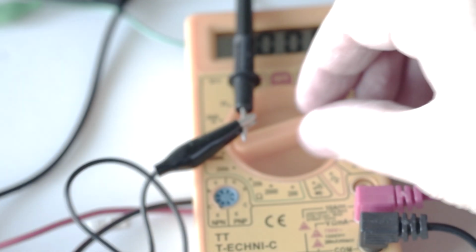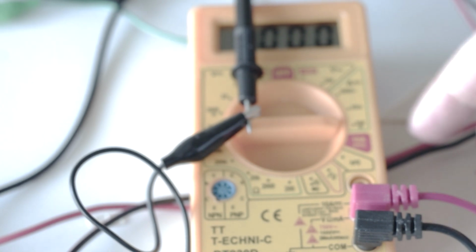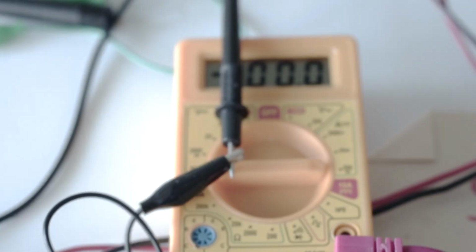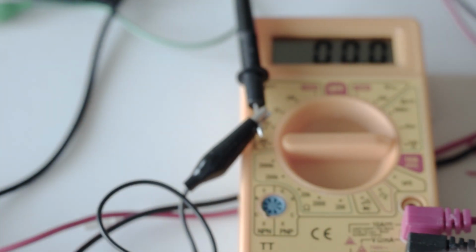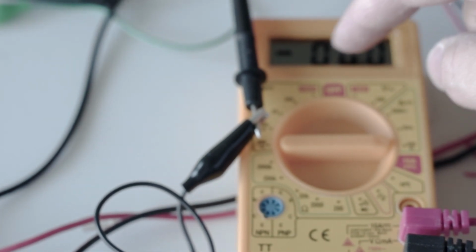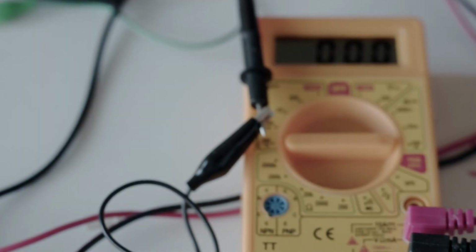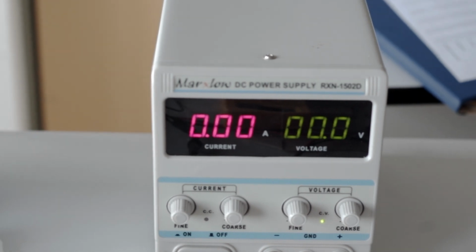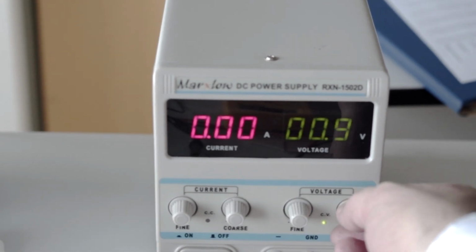I will put this. Okay, so I think our multimeter is not very good. You can change the 1 kilo ohms to a different value, but for now let's see how it will measure. This is like 200 milliamps maximum at the moment, but it should still be okay because I can measure up to 1 digit, so it can give me 1.6 milliamps. So let me turn off my power. Now we are ready to give voltage to the circuit. Power up the circuit by 5 volts.